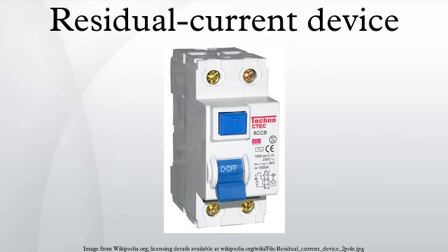A residual current circuit breaker with overload protection combines the functions of overcurrent protection and leakage detection. An earth leakage circuit breaker may be a residual current device, although an older type of voltage-operated earth leakage circuit breaker exists. Residual current device is a generic term covering both RCCBs and RCBOs.